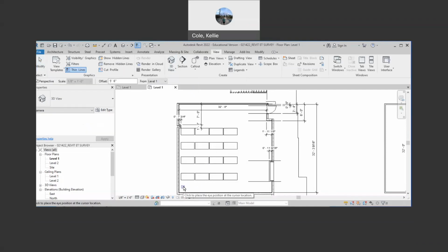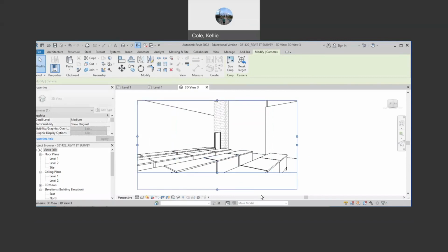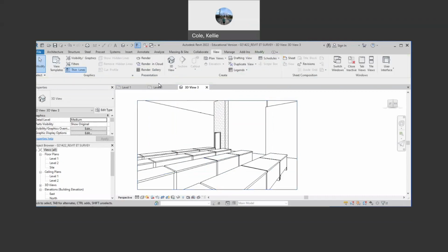And then we're going to position ourselves in our classroom as if we're in the back left corner. Click once and drag your cursor toward the door. So basically what we're doing is I'm saying, I am the camera and my view angle is out from me past the doorway. Click again. Yes. And we have a 3D view. All right. The thing that we notice, you can grab the little grabber buttons on the sides and make this wider, taller. But you'll notice that our ceilings aren't quite as high because we didn't draw a ceiling. So let's draw a ceiling and then we'll look back at our 3D view.